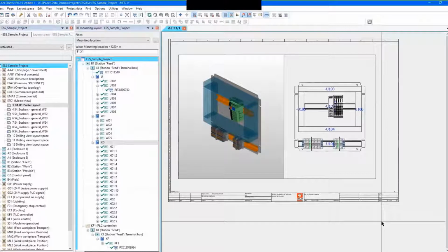You can do heat calculations from it because it's capable of working out how big the panel is. You can tell it what the parameters are for the control panel: the external temperature, what the ambient is, what the max internal temperature should be. It knows from the components how much heat they generate, so it's able to calculate a total power dissipation, which, for Rittal, you can add directly into the Rittal Therm calculation tool, and it will offer you an appropriate cooling solution if necessary.